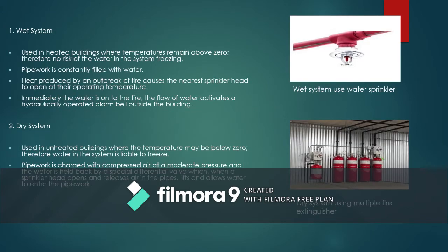wet system, used in heated buildings where temperatures remain above zero, therefore no risk of the water in the system freezing. Pipework is constantly filled with water. Heat produced by an outbreak of fire causes the nearest sprinkler head to open at its operating temperature. Immediately the water is on the fire, the flow of water activates a hydraulically operated alarm bell outside the building.